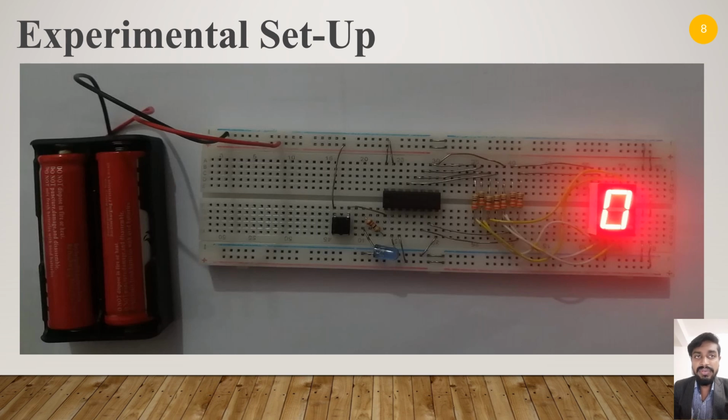This is useful if you have many display panels, because you can switch them on only when required, thereby saving power. For a simple GCSE-type project with a 7-segment panel, it is best practice to tie this pin high to the positive voltage rail. The clock inhibit function at pin 2 is used when you want to stop the count by blocking the clock signal at pin 1.